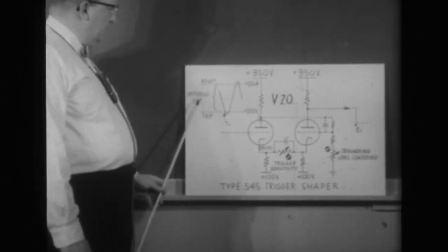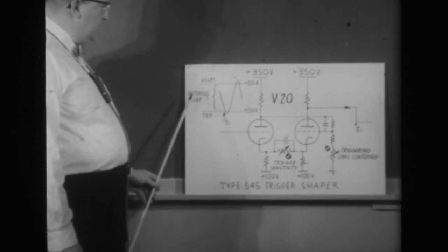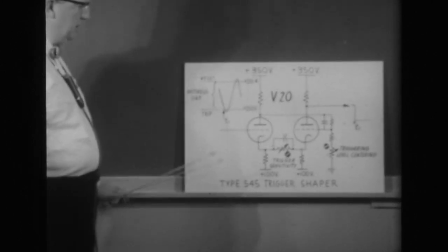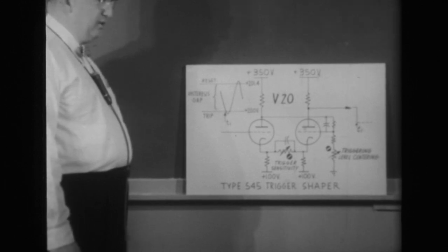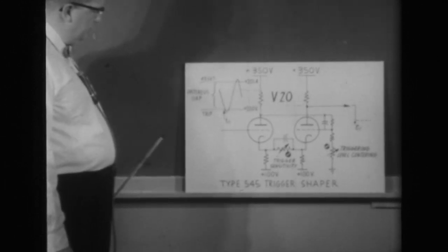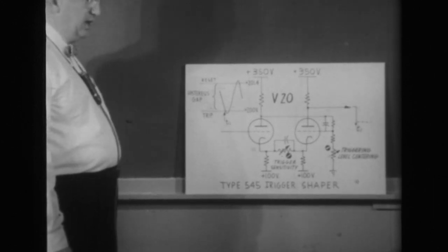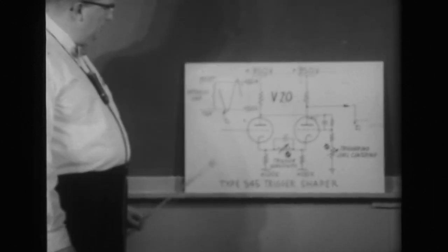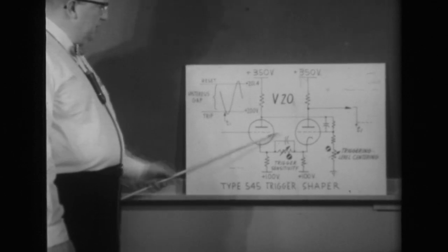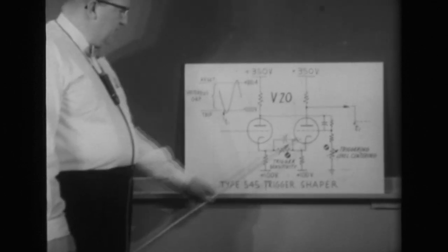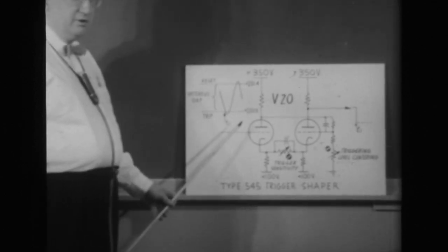We're interested in making that hysteresis gap as wide as possible and still make the instrument perform within catalog specifications, which says that a 200 millivolt square wave applied to the external trigger input of the scope shall make this trigger shaper circuit snap back and forth through its cycle of operations.